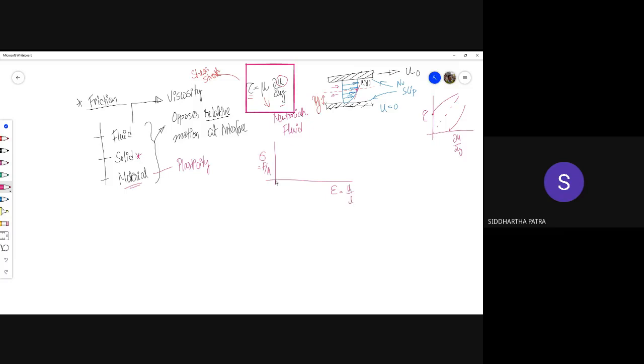And that in the first part obeys Hooke's law, but up to, let's say, a given point, which is the limit of elasticity, a so-called elastic limit, can be approximated as something called a yield stress. And beyond yield stress, the stress changes with strain with a much flatter slope. Okay, much flatter slope. It's like this.